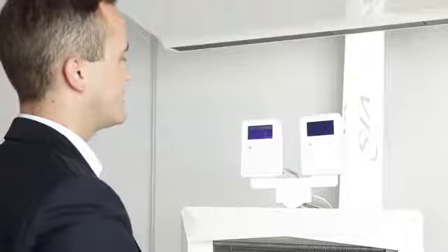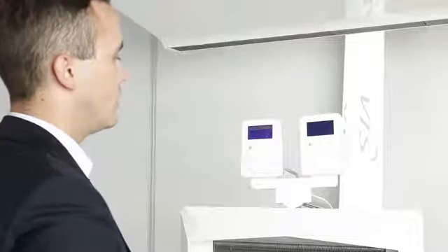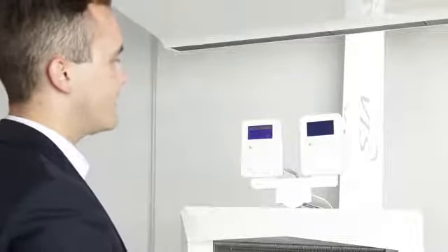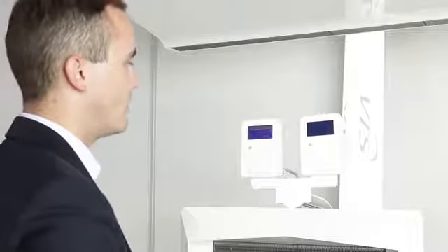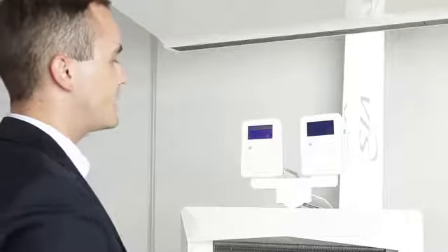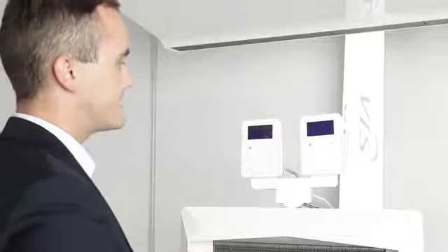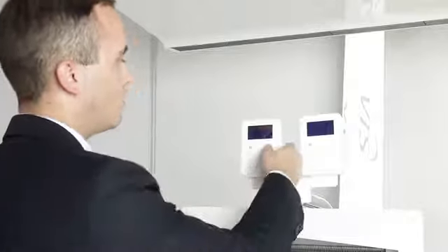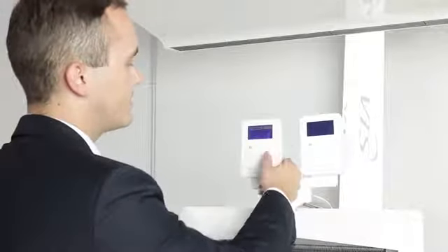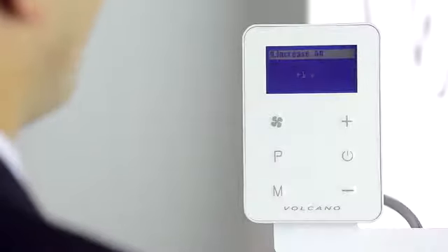The ninth advanced setting of the Volcano EC Controller allows us to increase the value of the output signal. For example, if the preset temperature cannot be reached in the automatic setting, we can change the value of the output signal. And so, plus 1 V.